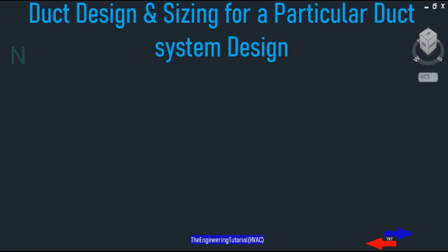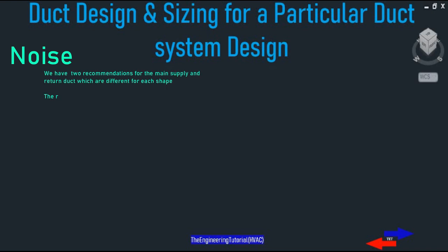The next thing we have to be worried about is noise. Noise can cause a problem if air travels through the ductwork too quickly. We have recommended and maximum air velocities, so anytime we are dealing with air velocity, that means we're talking about feet per minute. We have two recommendations for the main supply and return duct, which are different for each.